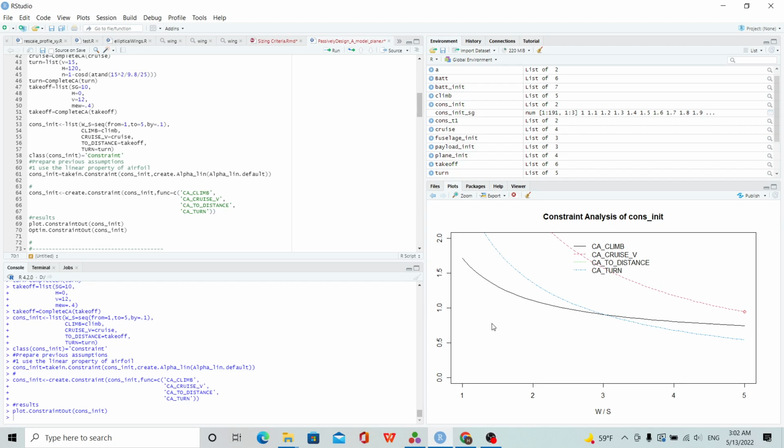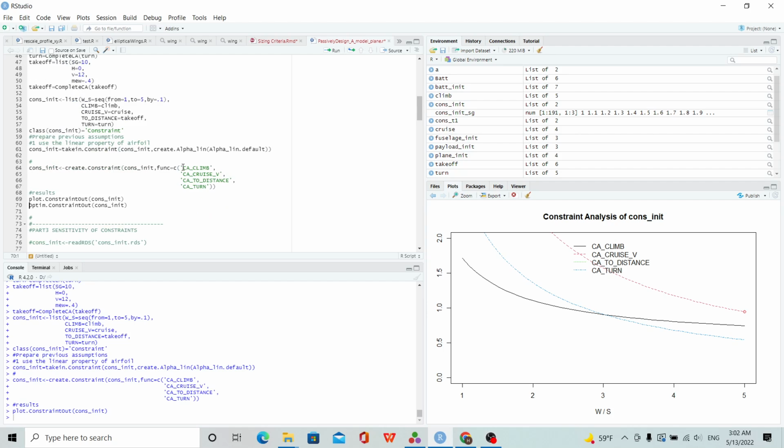So why is this important? This helps you to select the least possible engine. The engine with the least thrust to weight ratio usually costs the least, and also is the smallest, consumes the least fuel, and is usually the cheapest and the lightest.